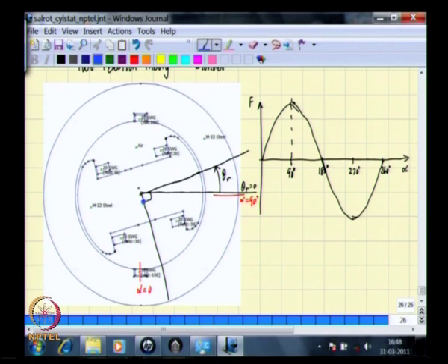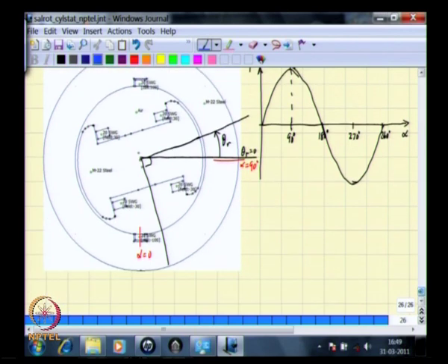As the rotor rotates, you always resolve this MMF, one along the pole face axis. If the rotor were rotated to some other axis, it would still be resolved along that pole face axis, and 90 degrees to that would always lie along the interpolar area. So this is what we do.